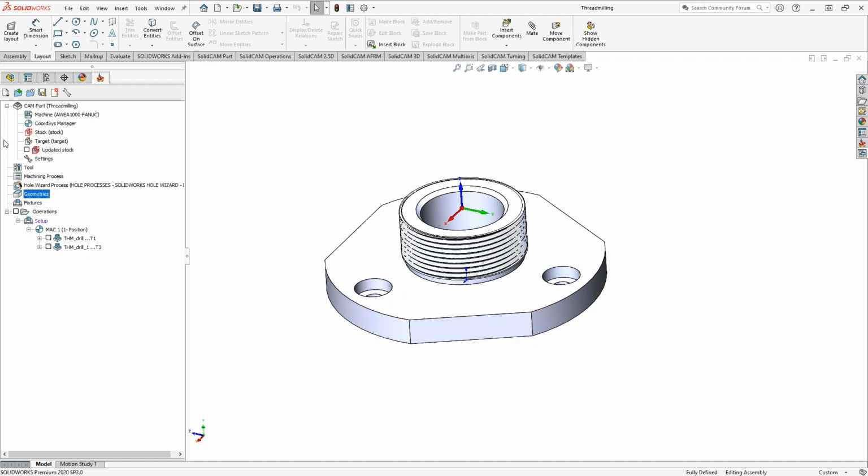And there are times when you've overloaded that folder. You've got so many different stock update models or so many geometries. Sometimes there could be a little bit of a glitch, and when you do that CAM part cleanup, your toolpath actually calculates a lot faster, kind of like what we're talking about here in terms of optimization. But it's always a good idea to get that done either while you're working on the part, especially when you're doing 3D work, or even when you're done.